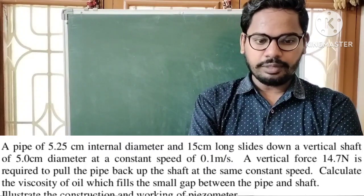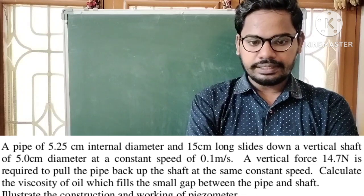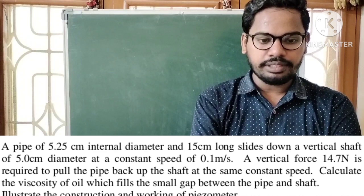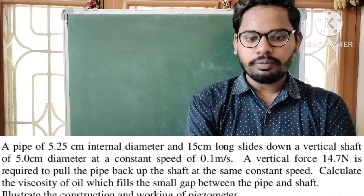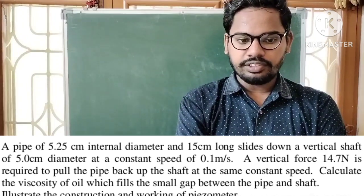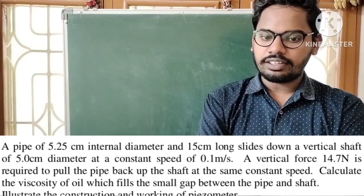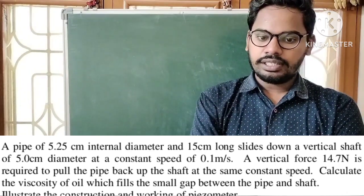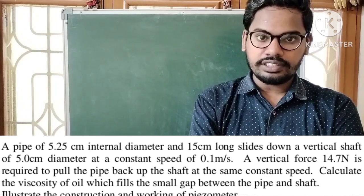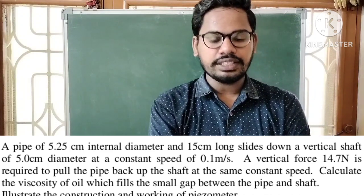A pipe of 5.25 centimeters internal diameter and 15 centimeters long slides down a vertical shaft of 5 centimeters diameter at a constant speed of 0.1 meters per second. A vertical force of 14.7 Newton is required to pull the pipe back of the shaft at the same constant speed. Calculate the viscosity of oil. Okay, here we have to calculate viscosity of oil which fills the small gap between pipe and shaft.